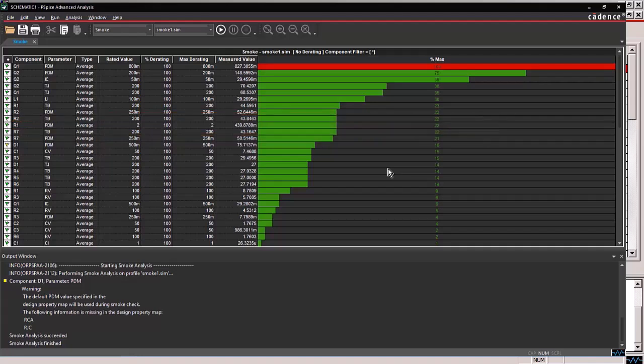Smoke used the maximum operating conditions supplied by vendors to calculate the safe operating limits of a component's parameters and compare them to our circuit simulation. Smoke then identified the problem parameters so that we could modify our design to make sure all the parameters meet operating conditions.